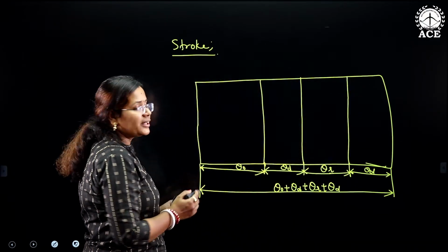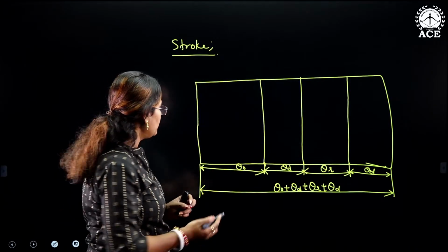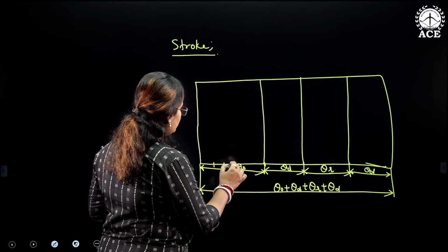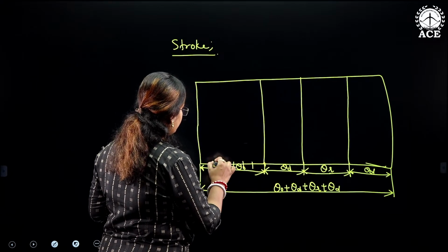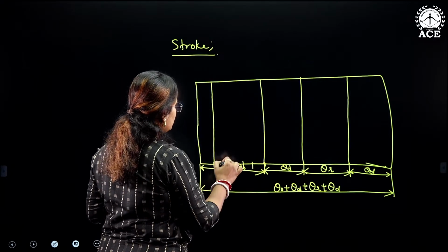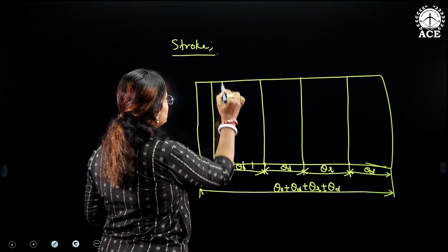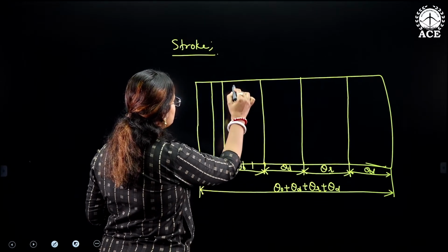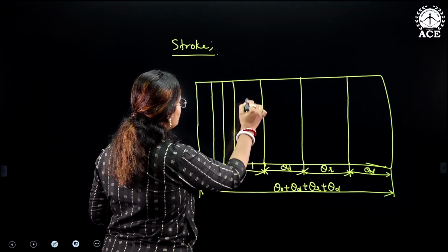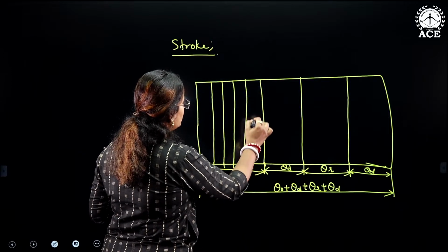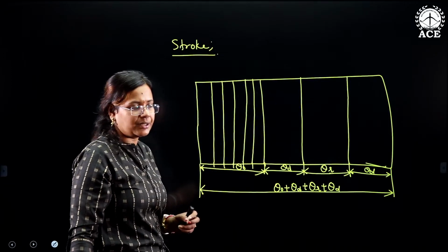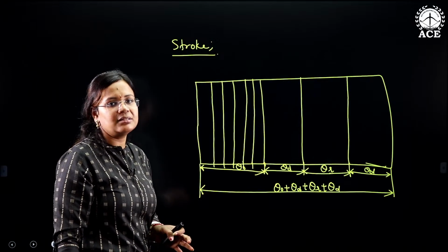Okay. I told you that each part you again divide into 6 equal parts. So 1, 2, 3, 4 and 5. Draw the vertical lines. This is nothing but the method of drawing the displacement diagram whenever the condition of the motion of the follower is given to be uniform acceleration and retardation. This does not follow any SHM motion of the follower.